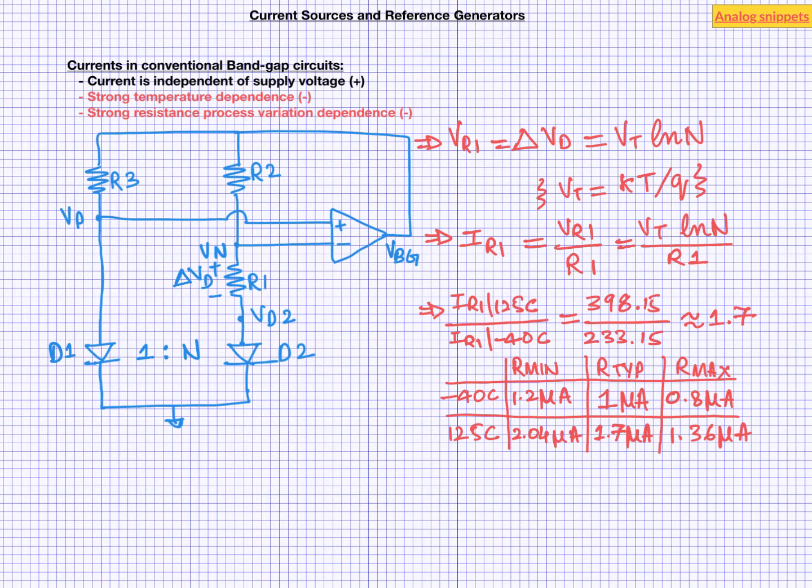So do we really use these currents in a practical circuit? In fact, we do. Even with these large variations, these currents may be just good enough for biases in certain amplifiers. But these currents are definitely not usable for precision applications, for example, to generate the local reference voltages or the reference of current drivers. So can we do any better?